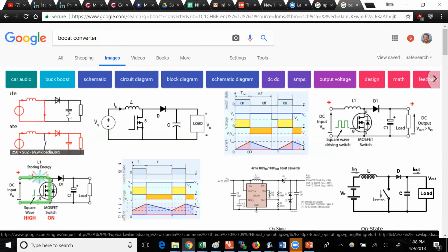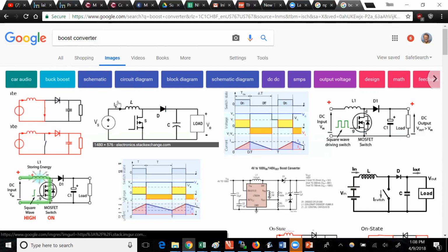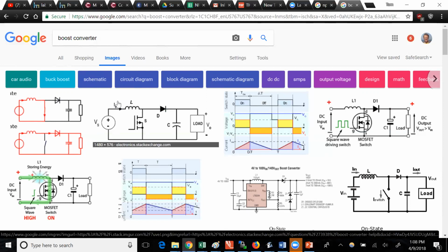The capacitor is sitting there with a high voltage, and it can't go back through the diode. It's blocked. It can only go out through the load. So if you keep pulsing it fast enough, you can provide enough charge. It's going to be oscillating somewhat, but it will get to a higher voltage than your input source.